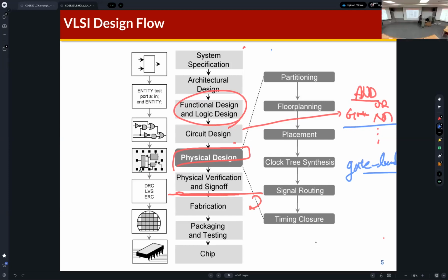And then at the synthesis, our module is translated into the netlist, which is a composition of gate levels, the basic gates. So simple modules are translated into multiple gates and then connections. And the gates are just AND gates, OR gates, exclusive OR gates, right? It's a very simple gate. But in order to build the various chips, we need to implement